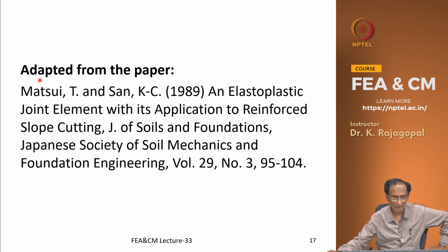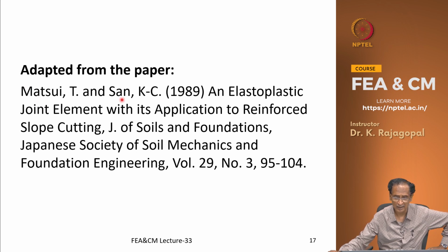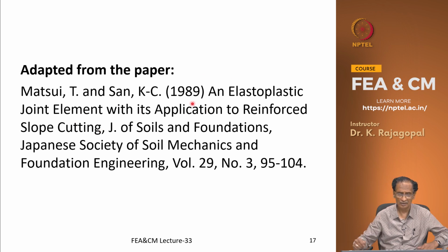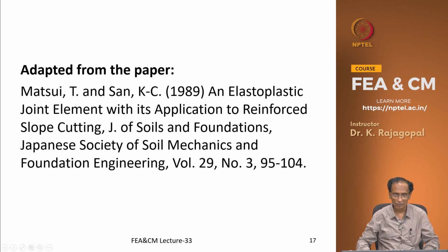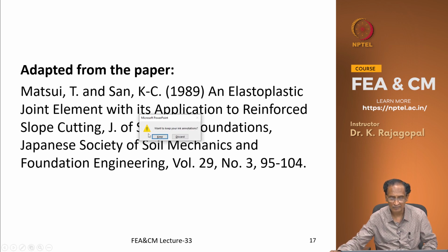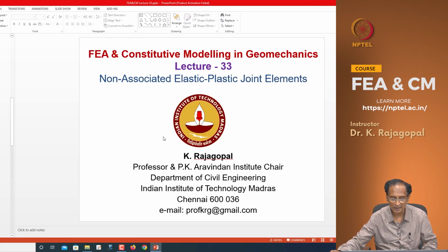This particular lecture is based on the paper by Matsui and San, Elastoplastic joint element with its application to reinforced slope cutting, whereas they considered only the associated flow rule. Here I generalized this for the non-associated flow rule with F and Q. Okay, so let us look at this program. Let me keep the annotations.